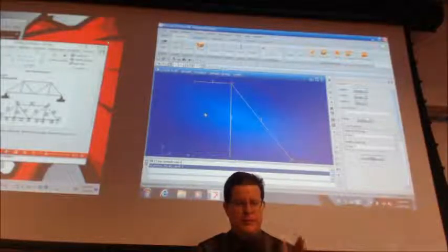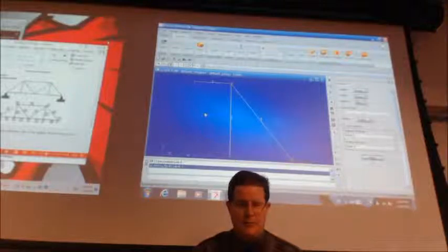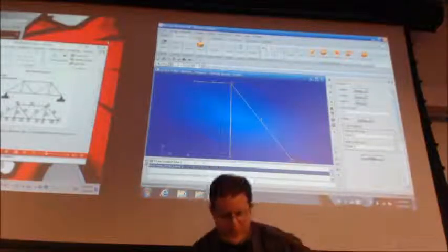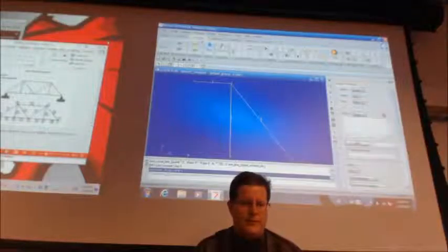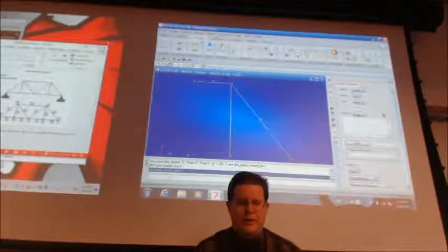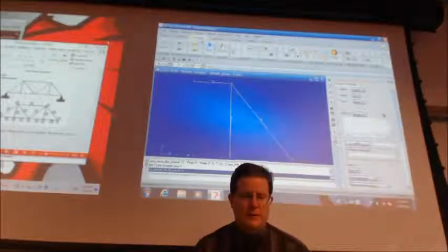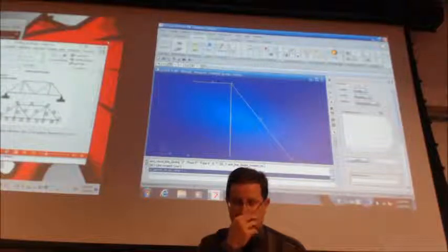So we've done our points and our curves, so we're basically done in the geometry tab, at least for the stuff we're doing. And we're going to go to properties. So what are we working on in here? Where are some of my tabs going? We want to be isotropic. We're going to do an isotropic material.